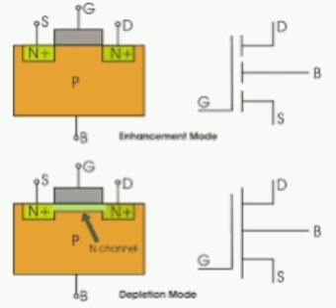Emitter junction breakdown voltage is smaller than the collector junction breakdown voltage. Emitter junction breakdown is due to Zener effect, while collector junction breakdown is due to avalanche effect.